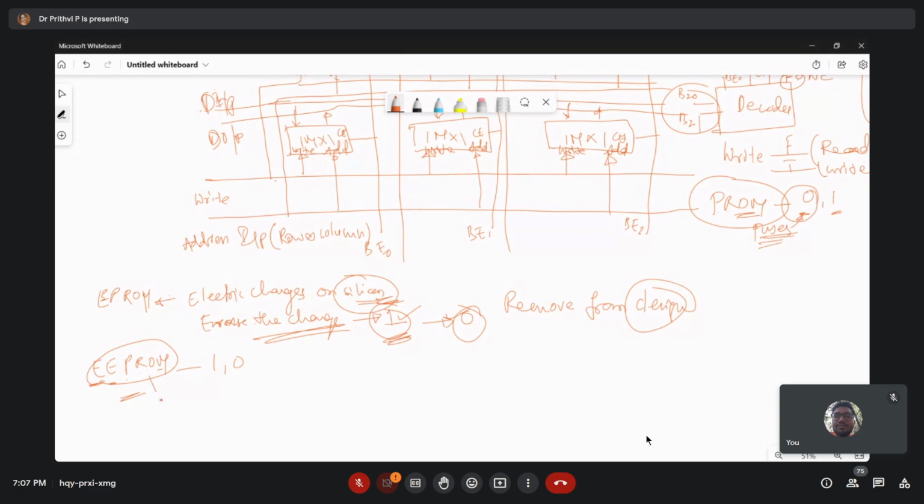There will be a specific program designed internally where if you expose this to 5 volts, it will be able to write the data in. The erasing will also be done without removing it from the circuit. Directly, you give an instruction or apply 5 volts, and it will give a value of 1 at the needed location. So that is one advantage compared to PROMs.